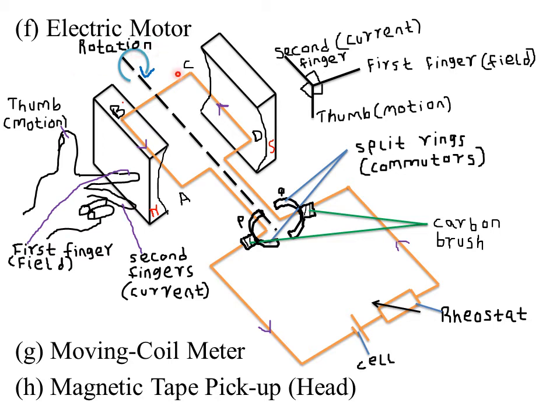Let's see what will happen to side CD or DC. If I apply Fleming's left hand rule, I will place my first finger, of course, in the direction of the magnetic field. Just take your left hand and hold the first three fingers mutually perpendicular, this way. Then place your first finger towards the direction of the magnetic field. Then place your second finger in the direction of the current. Now remember, for the case of DC, the current is moving from D towards C. So you will place your second finger.